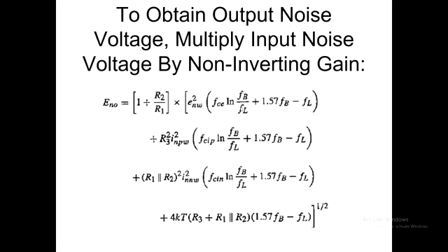We can't do that over here, can we? Oh dear. What are we going to do? We can go to the drama of putting in pi on 2 times 100 kilohertz, or we can just put in 100 kilohertz, and basically the answer to that question is who cares, because it's going to make such a little difference under the log.